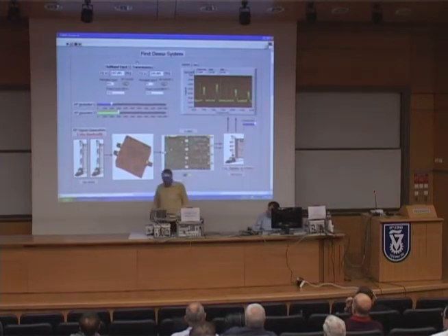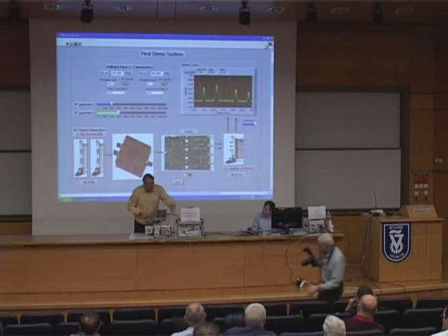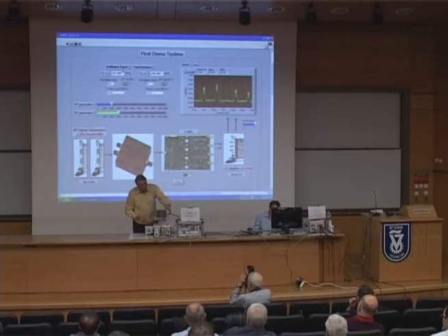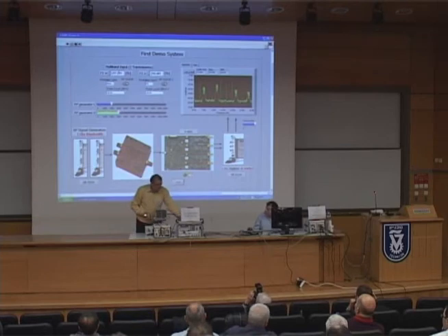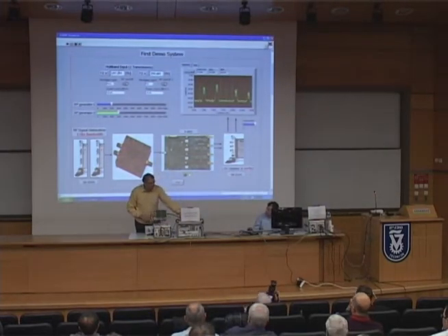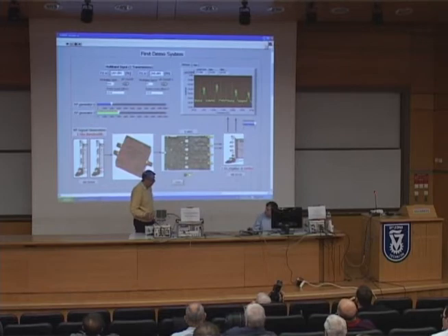I have to speak louder, but you see here the demo system, which consists of the RF area, which is producing our signal. The two signals from the two generators are combined, and it goes from here into the modulator card, which has 4 outputs. I'm currently feeding 2 of the outputs to the digitizer and 2 outputs to the real-time scope, which has 6 gigahertz bandwidth, and we use it to show you the real input.